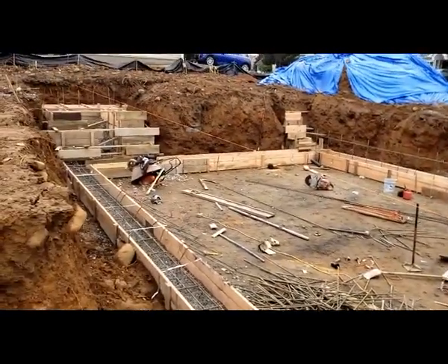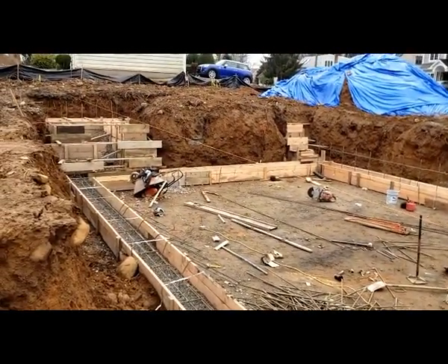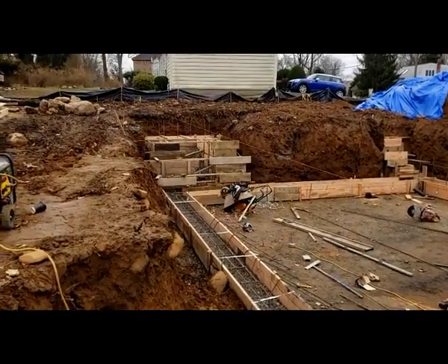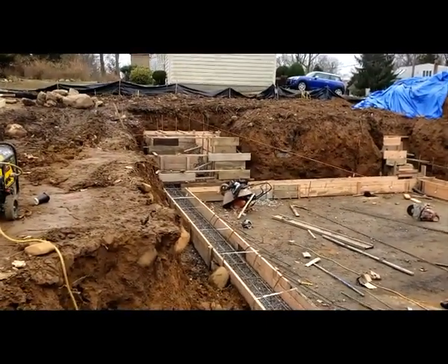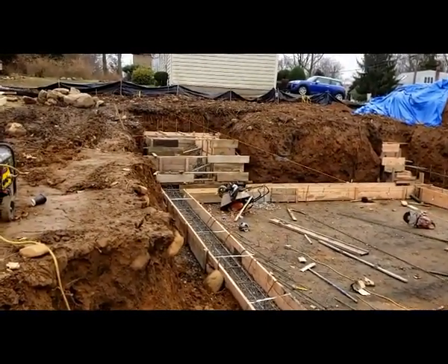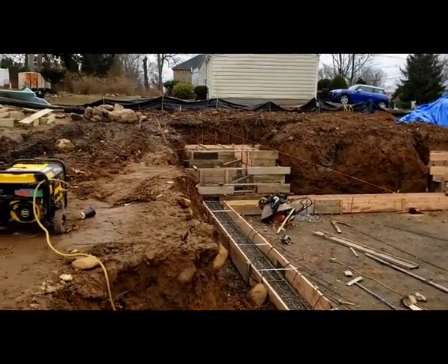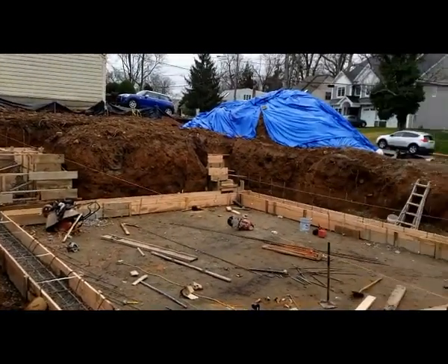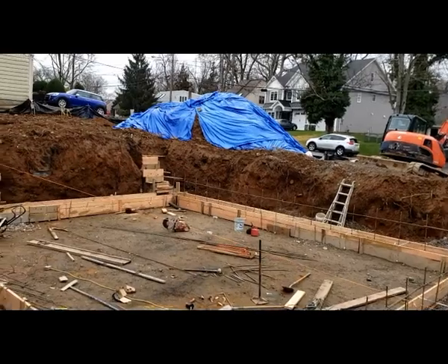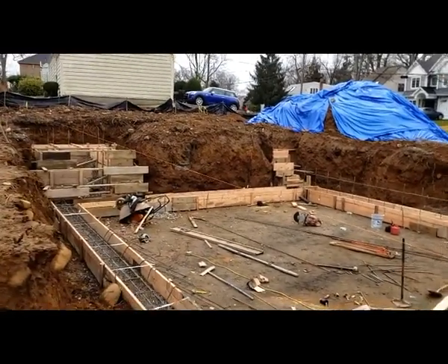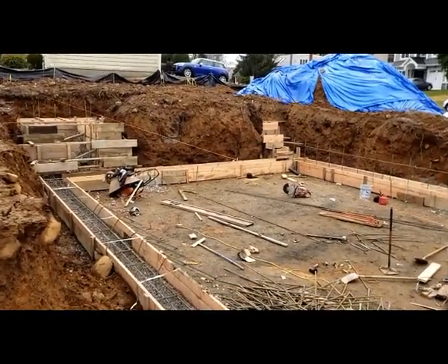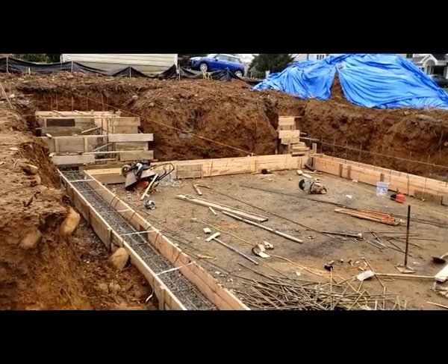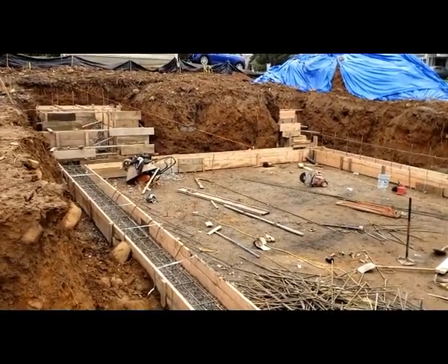Today I will be going over the common checklist. So if you want to write it down, if you want to pay attention, write this down. I'll try to put it all together and send it to you and put it on my blog. So first thing, you need to check the elevation. You want to make sure the top of the footing is at the right elevation. If the top of the footing is wrong, it means the walls will be wrong.